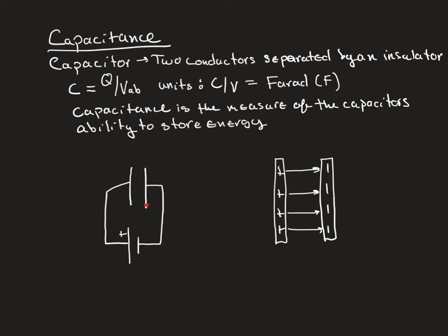And the electric force caused by the fact that now there's a buildup of charge here generating an electric field is actually going to push electrons off of the other plate and through the circuit. So instead of electrons flowing from one plate to the other, there's a buildup of charge here which then pushes charge off of the other plate until you have a neutral set here. So one plate's going to be positively charged because it lost electrons, and one plate is going to be negative because it gained electrons. But it's the electric force due to this buildup of charge here that's actually going to push charges off of here through the circuit.